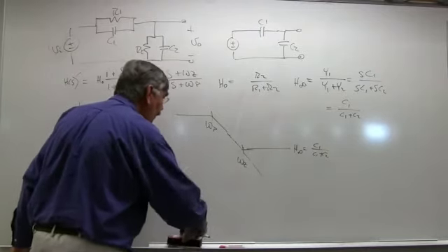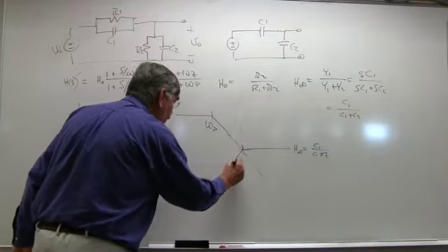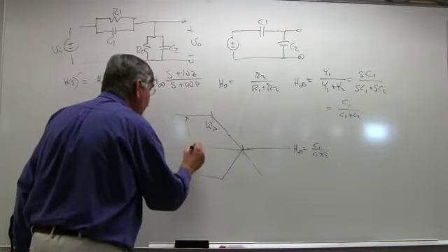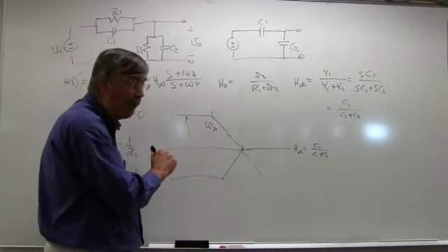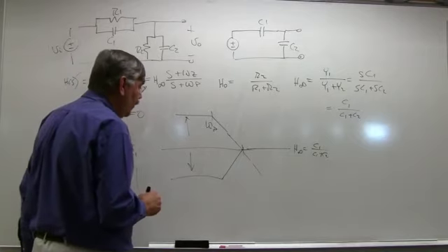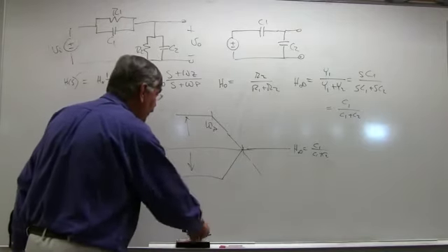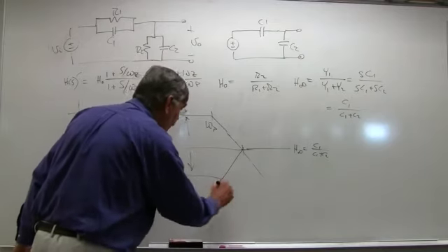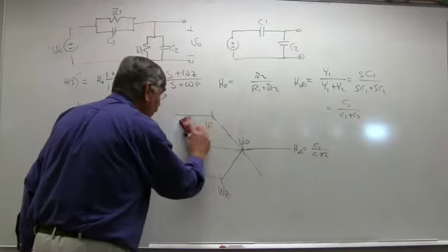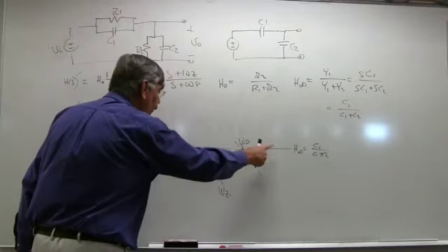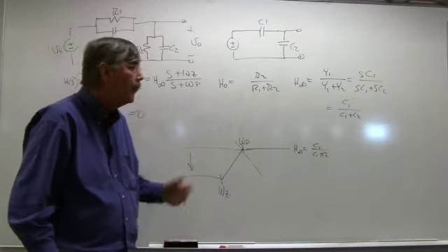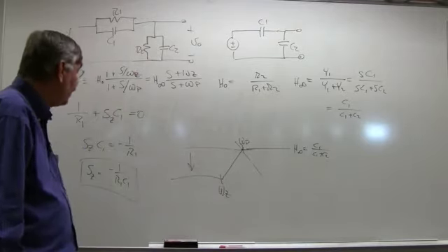And maybe you'll see somewhere a bass control where you can swap around between several versions of this thing. You can increase this and get an increase in the low frequencies, a bass boost, or you can change the circuit around so that this thing attenuates the low frequencies. If it's in this attenuation form, this is the omega 0, and this is the omega associated with the pole. So you get two different transfer functions. Anyway, this thing can be used as a bass control or as a treble control, so it's kind of a handy circuit that gets used in a lot of applications.